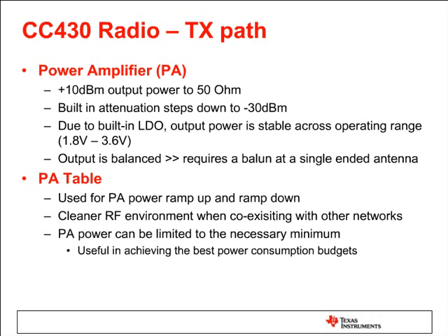And all these values are provided by the tools that we give you. So we have this SmartRF Studio, which can give you every value you need to write into the PA table. You have to do no real calculations. You just set your maximum power that you want, and if you're doing amplitude shift keying, it'll spit out these values for the PA table. So that's very nice.